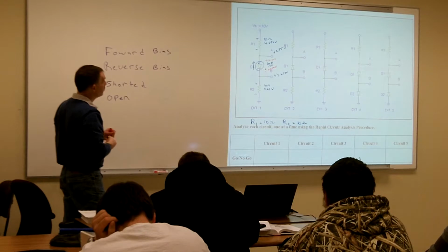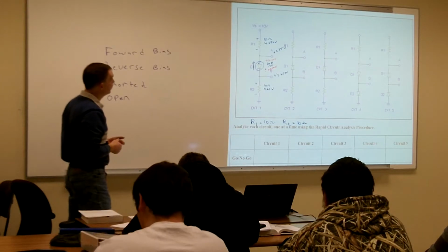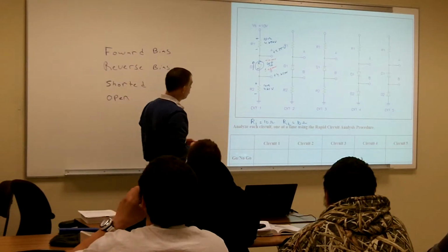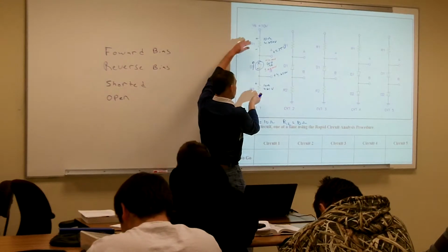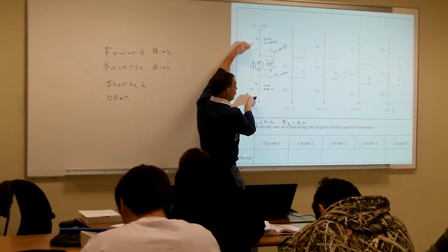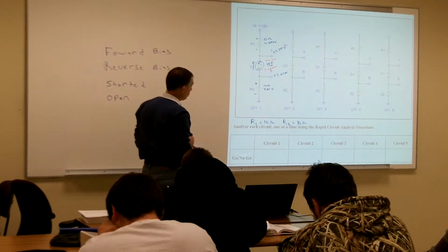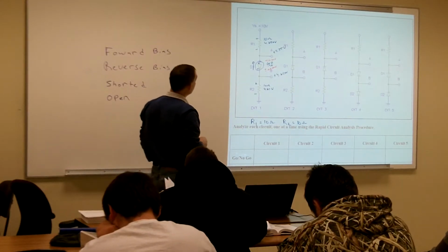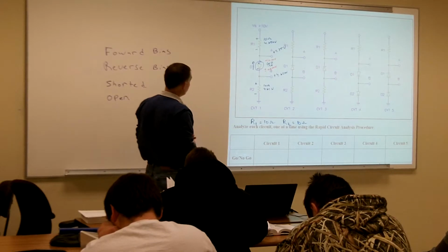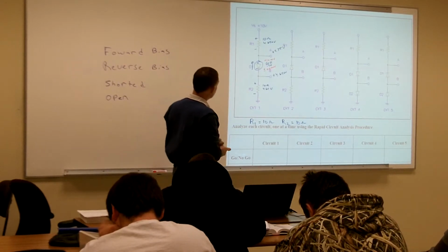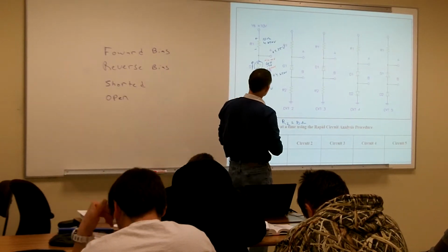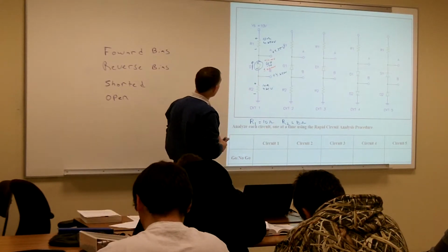All right. So give the diode its voltage first. If we had two different values of resistors, then we'd have to use the voltage divider formula. Otherwise, since they are both equal in resistance value, we just divide up the remaining amount of voltage across the two.